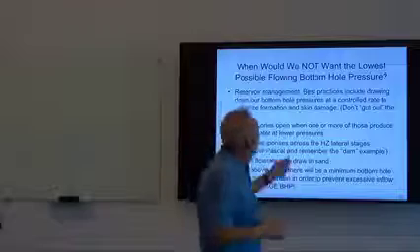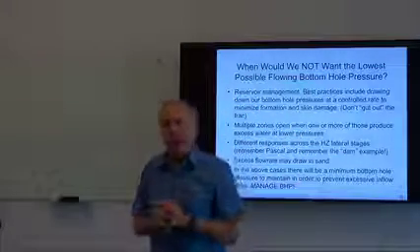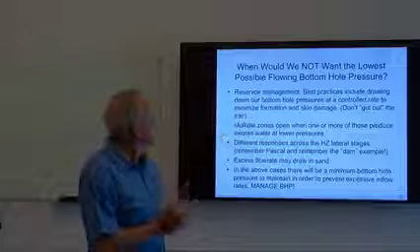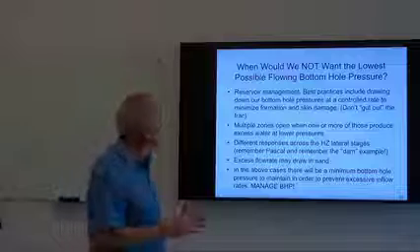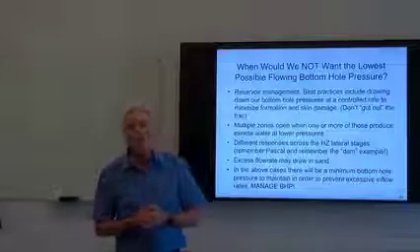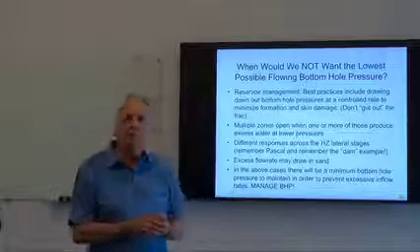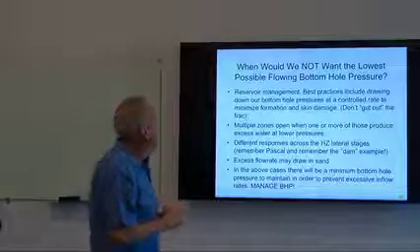If we create damage in the formation by pulling that out, sometimes here in North America we talk about it as gutting out the frac. We don't want to do that, because we spend a lot of time and effort and money to fracture our wells and to complete our wells this way, and washing out that frac sand is problematic.